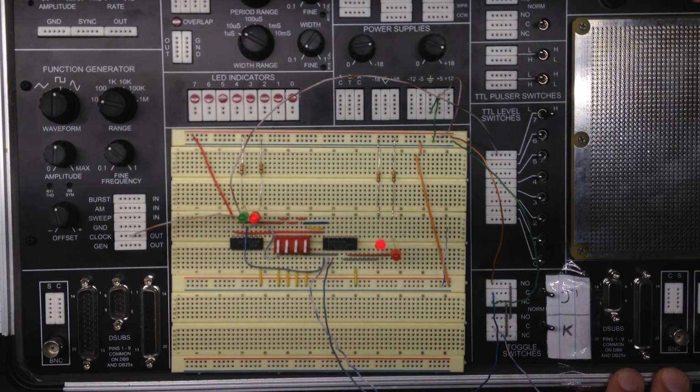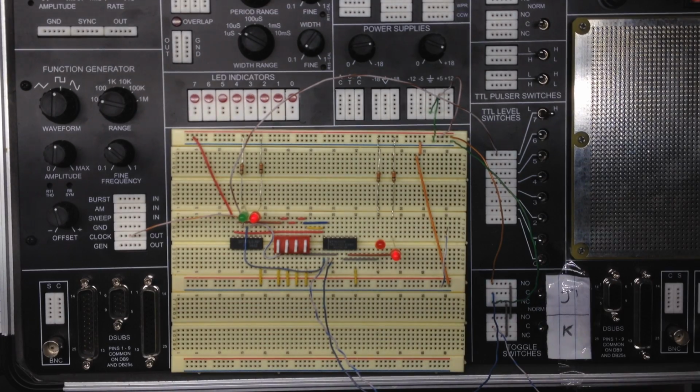What we're going to do now is walk through the other states that are available with our inputs, as long as we have a high on the preset and on the clear. The first that our table lists is if we have a high on preset, high on clear, a downward edge on the clock, and low on J and K. That means that the current state of Q and the current state of Q naught will stay the same.